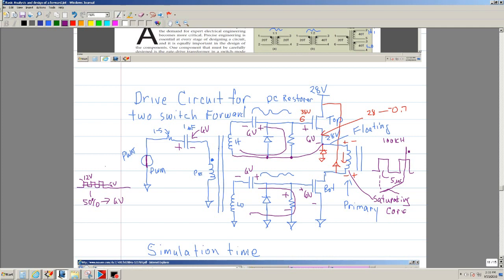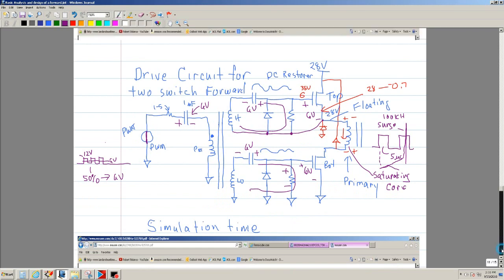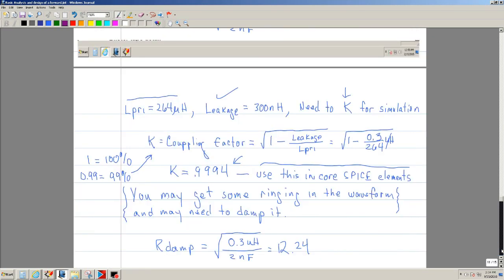So you have to be careful with that. That's the only drawback: these capacitors, if they discharge, have to discharge fairly fast, and your circuit may or may not be able to withstand that surge current. So you're going to have surge current. That's the gotcha you have to be careful of. If it's low power, it probably won't affect you too much, but if it's high power, then you may not be able to use this circuit.